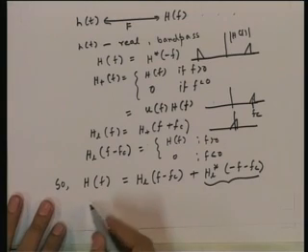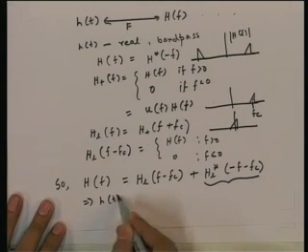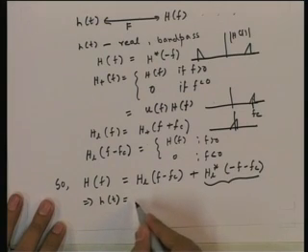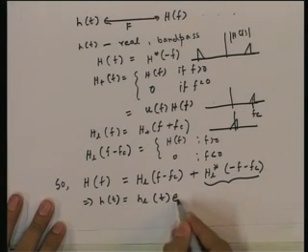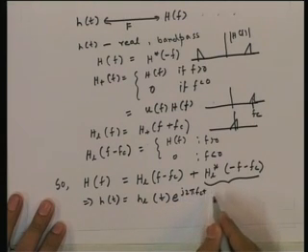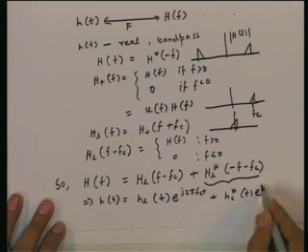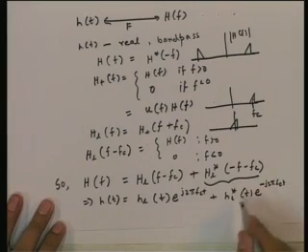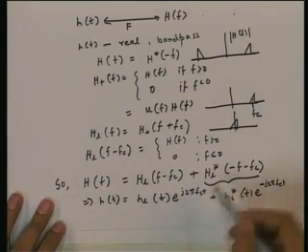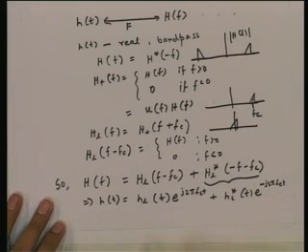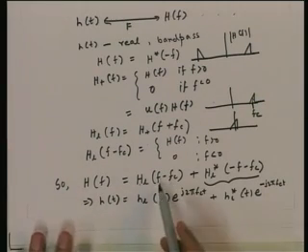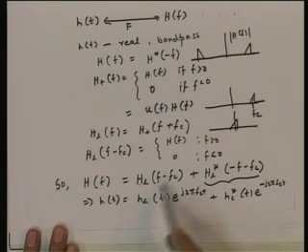So from here we can also write that h(t) is h_L(t) e^{j2πf_c t} plus h_L*(t) e^{-j2πf_c t}. These are basically the inverse Fourier transforms of these two. So h_L(t) is the inverse Fourier transform of H_L(f). Then we can use the well-known properties of Fourier transforms to see that the inverse Fourier transform of this is this.